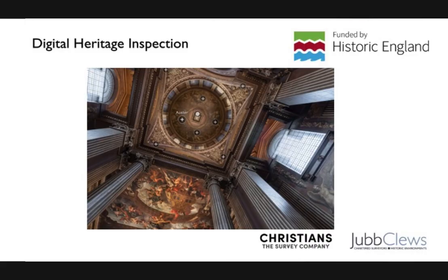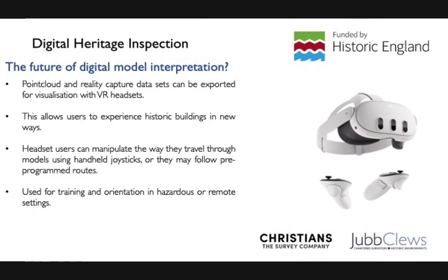Yeah, 100%. Within a laser scanner, it takes photos anyway, so it gives you that 360 pano deliverable anyway. The quality of the image depends pretty much on the scanner that you're using. We have a scanner that we can take off, put a digital SLR in its place, and then you've got 12 61-megapixel images. So it's a higher resolution than any 360 camera, almost like a gigapixel image.